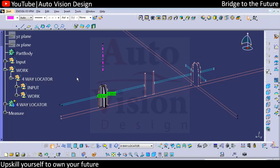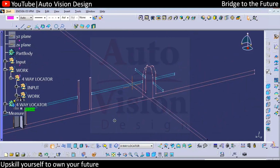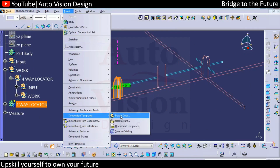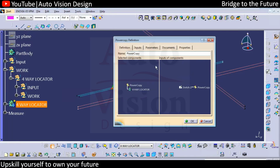Okay, so now we'll check how we can create that power copy. Before that, we need to have the point in this area. To run that power copy, we'll set the power copy dimension first. So go to Insert, then Knowledge Template, Power Copy. Once you select that, it will ask for the inputs.